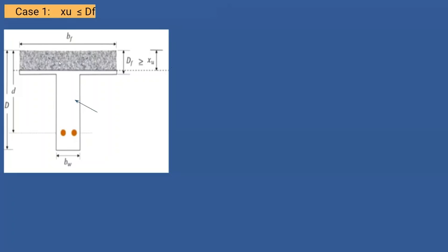As per your assumptions in limit state, the concrete below the neutral axis is not considered. मतलब हम लोग का जो कंप्रेसिव फोर्स देंगे फॉर एनालिसिस, ये न्यूट्रल एक्सिस का ऊपर वाला पोर्शन ही they will provide the compressive force, and tensile force कौन देगा? ये reinforcement. As it is. So all concrete below the neutral axis is ignored.